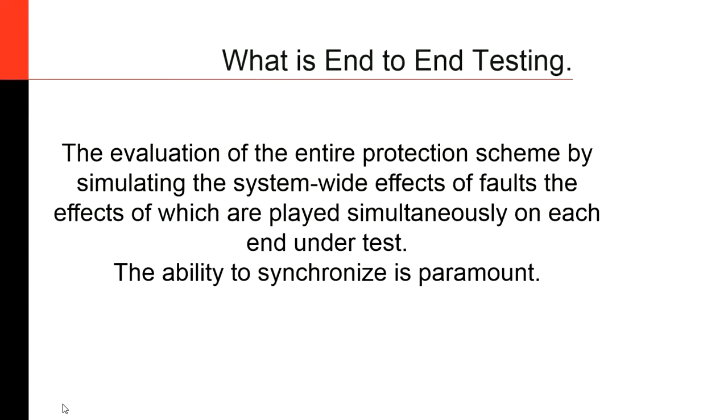So this is a definition that I came up with about what is end-to-end testing. You will find as many definitions as people approach in the field, but everybody agrees that end-to-end testing is a way to evaluate the entire protection scheme by simulating the effects of faults on both ends of the line, which have to be played simultaneously.